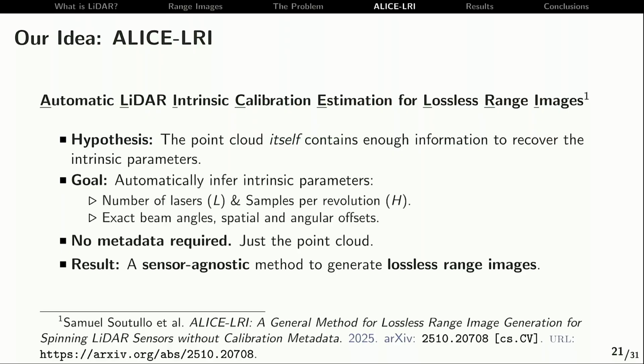Once you do it, you can save the parameters and reuse them. And then the important part, the intrinsic-aware projection and back projection, runs in the order of 10 milliseconds each. So it's feasible for real time, because if you work with LiDAR sensors, you know typically the real-time threshold is around 100 milliseconds, because usually these sensors take 10 samples per second. So basically the method works in real time.